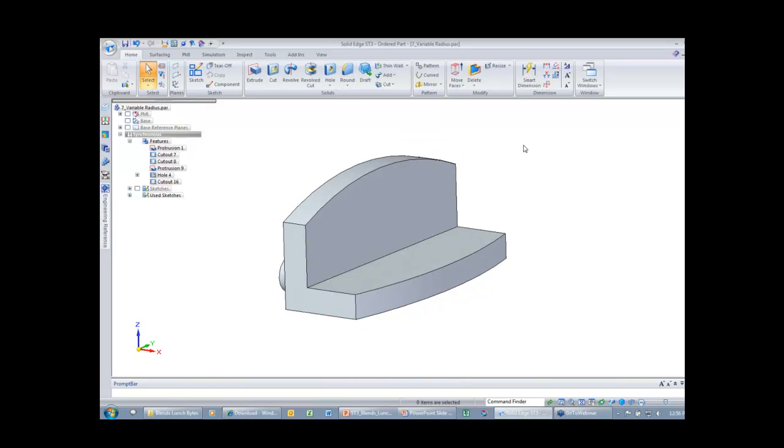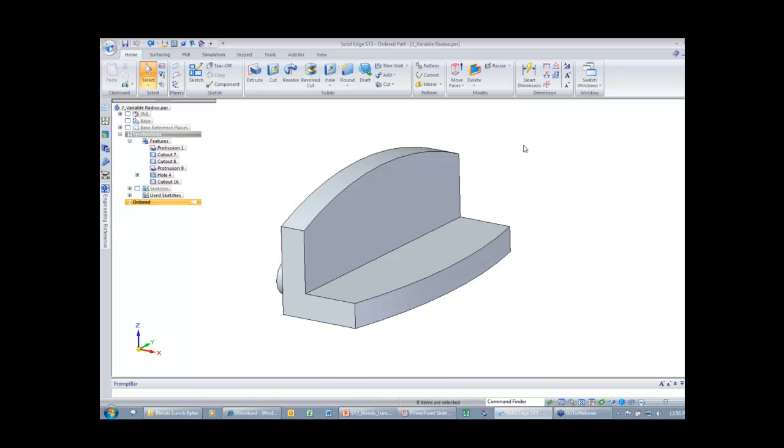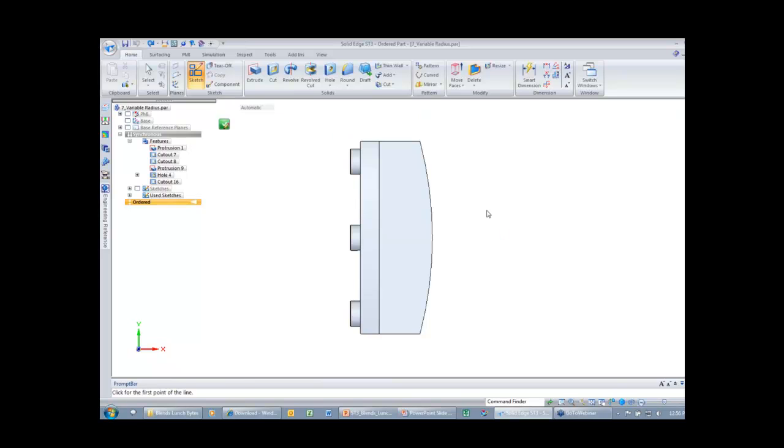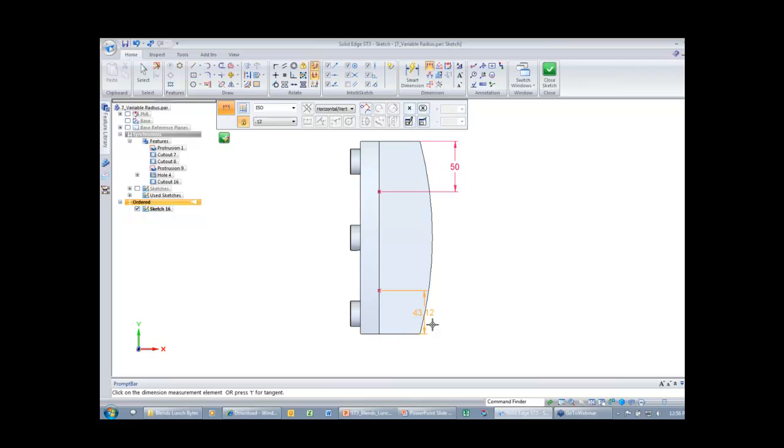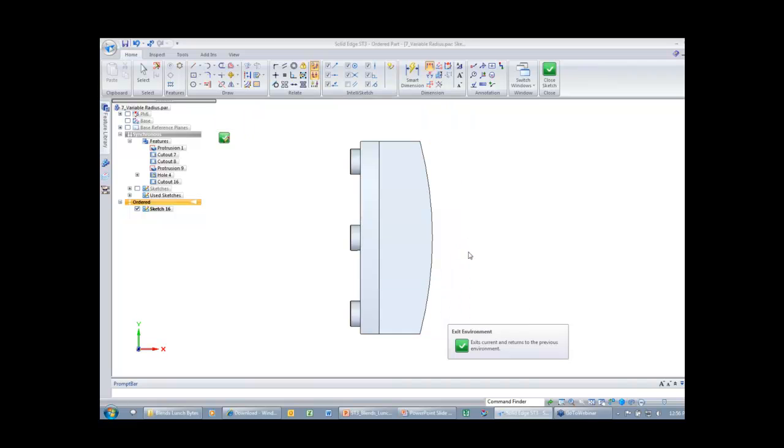A kind of a tip and trick to take that a little bit farther. You notice I can do endpoints and a midpoint with that particular example. What if I want a little bit more control? What I'm going to do is come in there and create a sketch, and I'm going to put some sketch points at that edge. Maybe I'll go ahead and dimension those, just kind of locating those points where I want them along the edge.